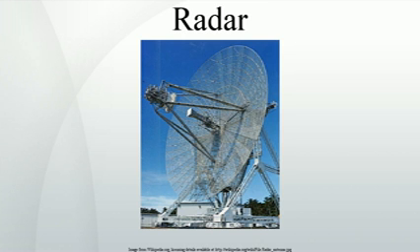Reflection. If electromagnetic waves traveling through one material meet another, having a very different dielectric constant or diamagnetic constant from the first, the waves will reflect or scatter from the boundary between the materials. This means that a solid object in air or in a vacuum, or a significant change in atomic density between the object and what is surrounding it, will usually scatter radio waves from its surface. This is particularly true for electrically conductive materials such as metal and carbon fiber, making radar well suited to the detection of aircraft and ships.